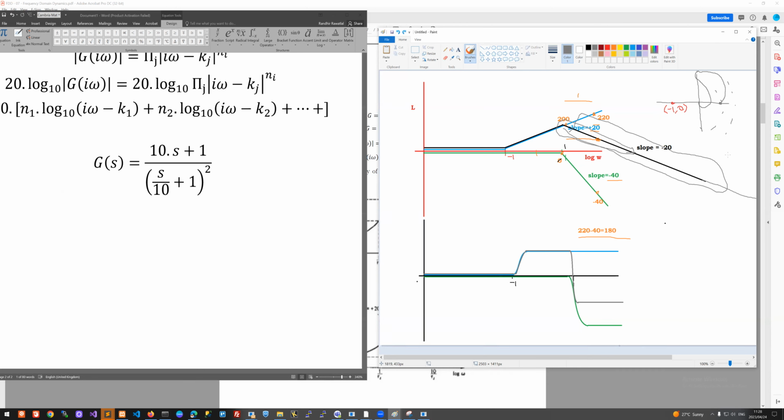So the concept here is that it's easy to draw Bode diagrams almost by inspection. I did it long and laborious, but if you just inspect this thing, you can see, okay, crossover frequency 1/10, 0, and then shove in a plus 20 here, and then crossover is 10. So just by inspection you can quickly draw a Bode diagram, and then you look at the different pieces and try to guess on your imaginary plane, how is that looking? And then you can tell whether you are going to encircle that.